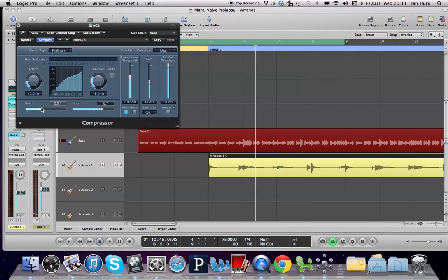Okay, notice that the gain slider is set to 4 dB, which is raising the overall level of the guitar signal. Over here, 4 dB. The compressor attenuates the parts of the signal that go above the threshold, then raises the overall level to compensate for that attenuation, because we're actually reducing the overall level because we're attenuating.